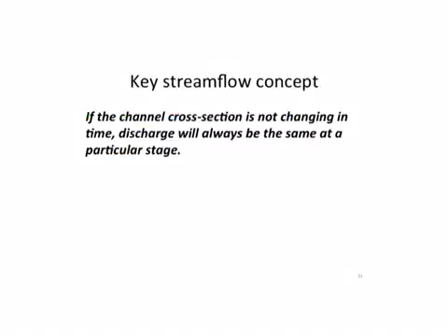So one key streamflow concept is that if the channel cross section is not changing in time, discharge will always be the same at a particular stage. So this word stage might be a new term to some of you. Stage is defined as the elevation of the water surface relative to a datum.